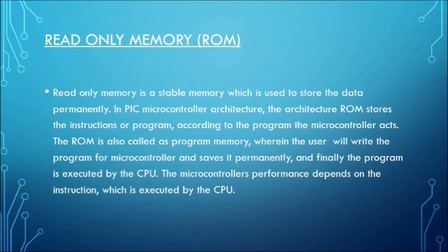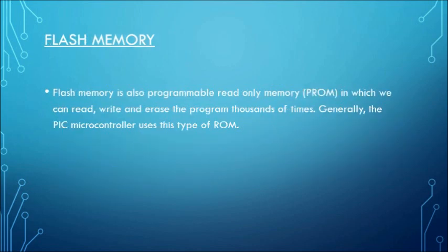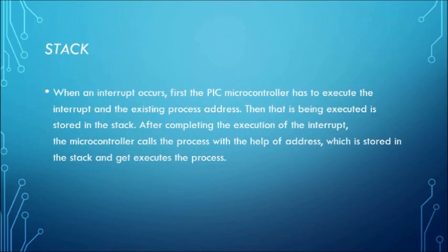In the PIC microcontroller architecture, the ROM stores the instructions or program. According to the program, the microcontroller acts. Flash memory is also programmable read-only memory, in which we can read, write, and erase the program thousands of times. Generally, the PIC microcontroller uses this type of ROM. Next, we have the stack.